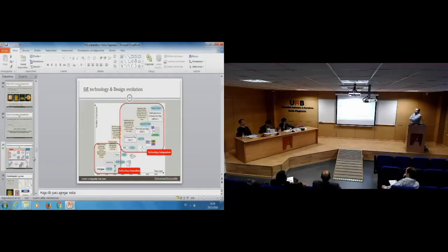Yeah. Well, my answer is, if you are going to go for eco-friendly and only additive manufacturing of printed electronics, it is still far away from implementation of high-performance circuits. If you need a high-performance circuit, the circuit still needs to be made either with silicon-based materials, or, if you are using organic materials, fabricated using clean room processes like photolithography.